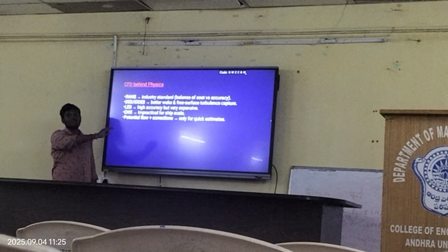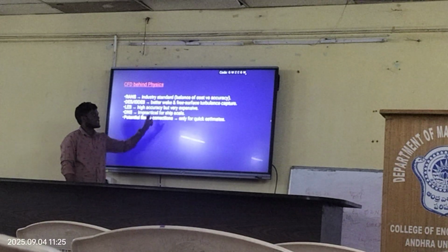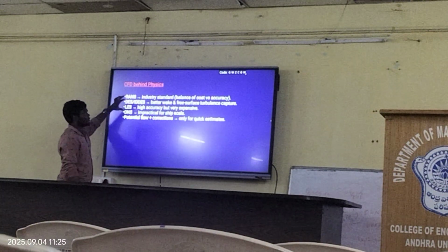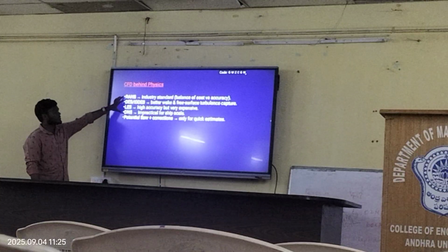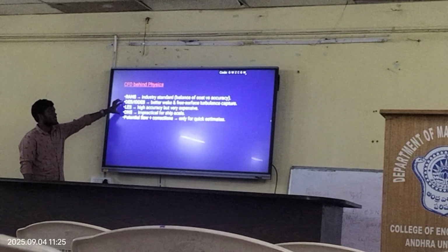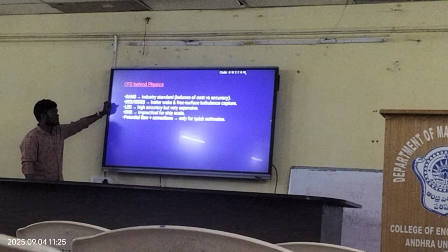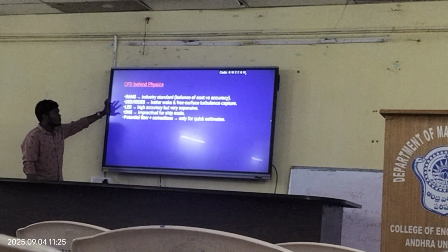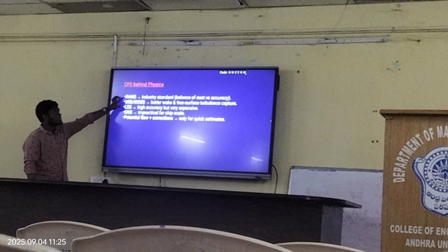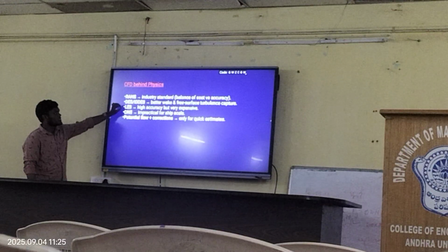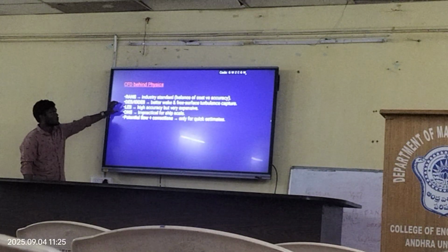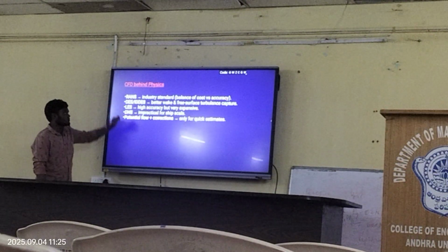But in the practical world, we deal with viscosity. So those are nothing but corrections. In our domain, Reynolds averaged Navier-Stokes equations and potential flow plus corrections are mainly used. These give approximate results with less error.